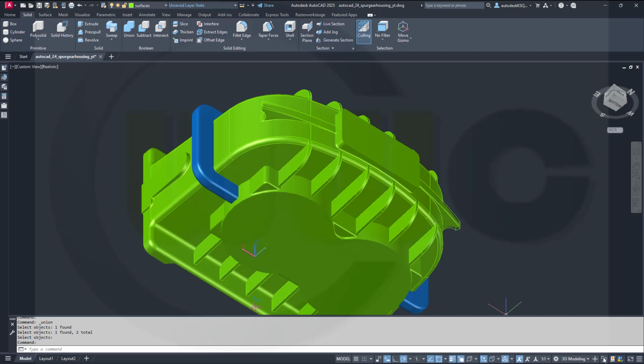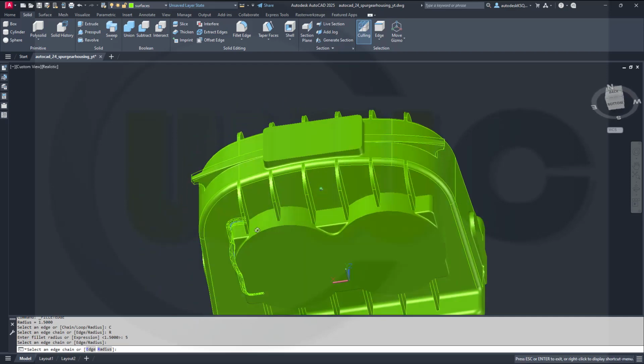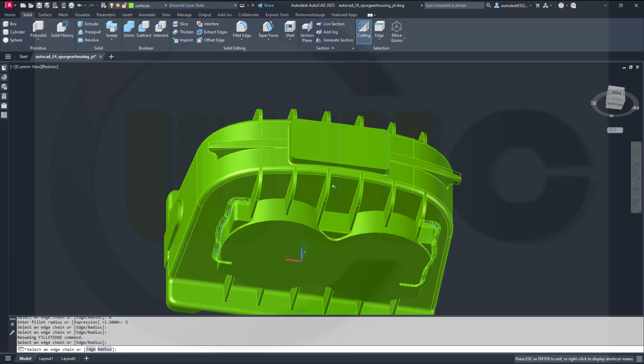Right click. Let's hide this for the moment, so it's better to see. So go for hide object, hide this one. Right click and make another fillet. This time it's 5 mm. Of course it's a chain and radius should be 5 mm. On this edge, yeah, it will not go around because I've already did those ribs. Yeah, but it's almost unavoidable.